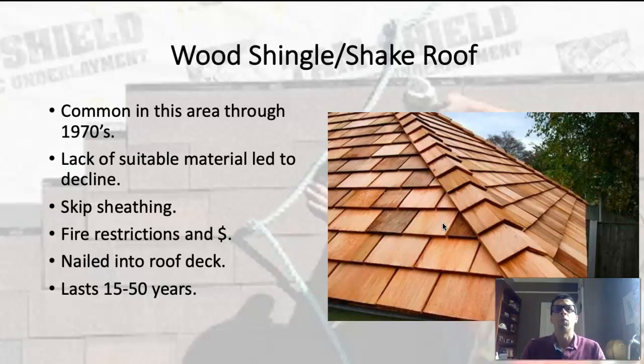So we're not really cutting quality old growth trees down anymore to make shingles and shakes. So we can get them, but the quality is lesser. Where they used to last 50 years, 60 years, now they're lasting 15, 20 years. So it's a pretty big investment, and they don't really last as long as they used to.